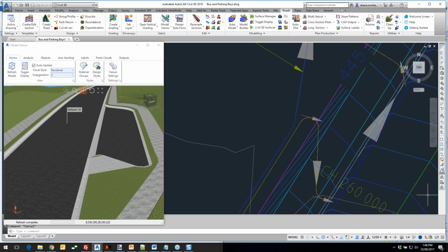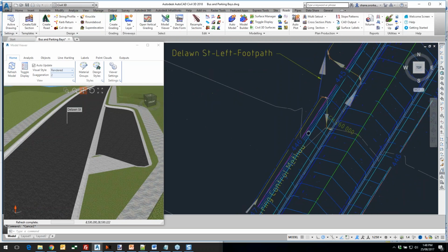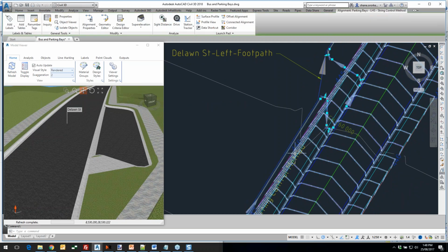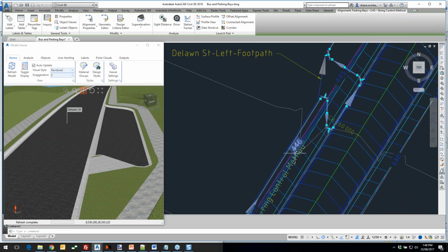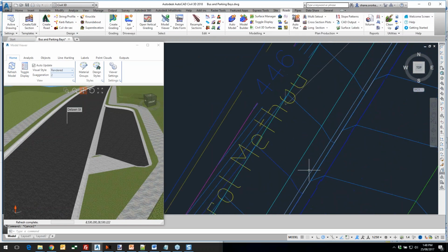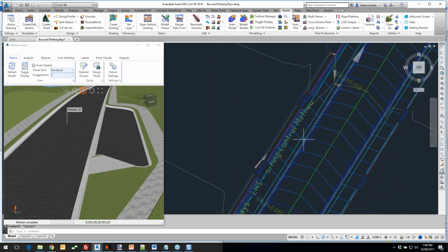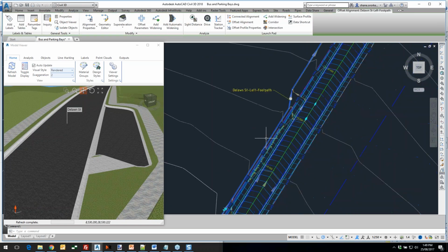Now, what you need to realize is that what we're doing essentially is sticking this design in between the current road, okay? And the current road has no dish at this stage, but we're going to put the dish in. It has a footpath, it has a batter. So the first thing that we will do is move the footpath away from the design we're going to stick in, and I have an alignment for that.